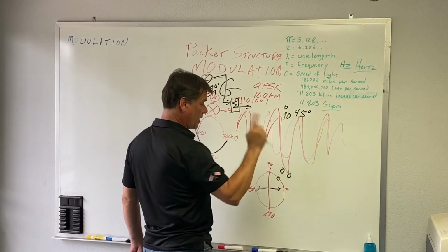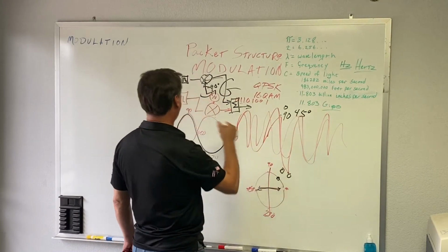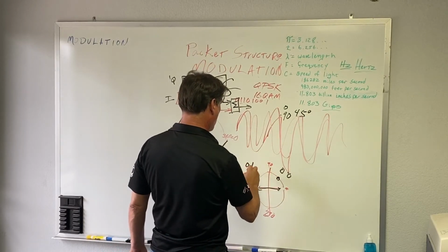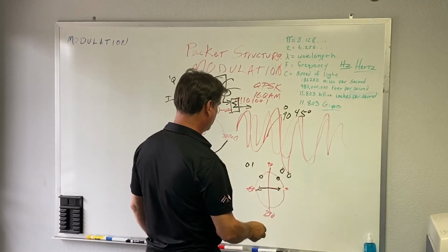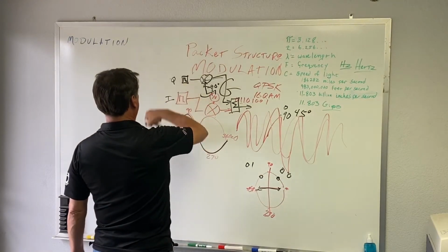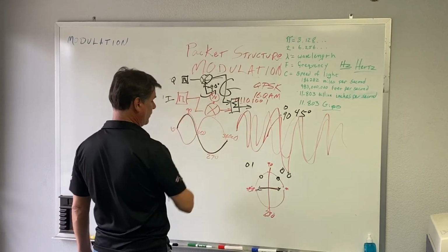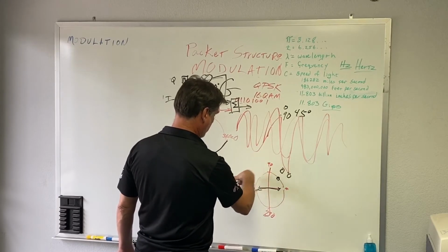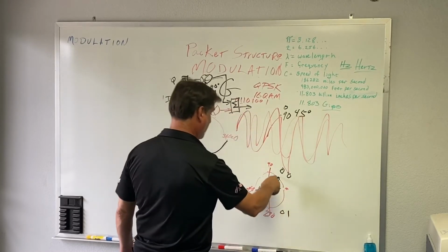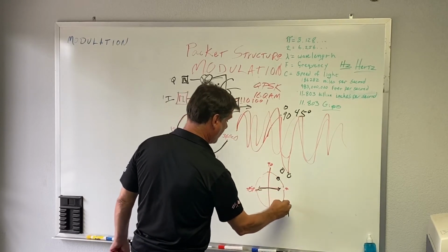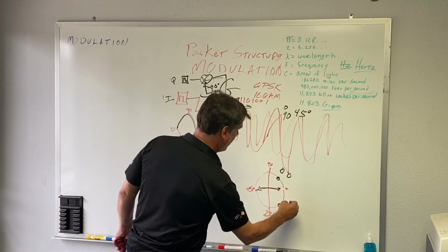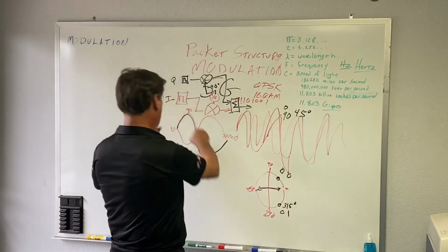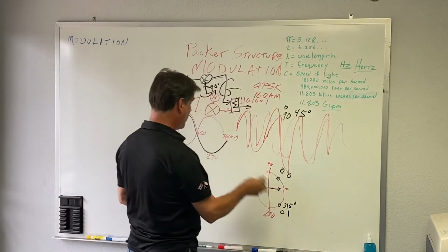When you mix these two, you get the difference between them. So if you go to a 1 here on Q, so that is going to be a 0, 1. We're going to shift it right there. Take that guy, make him a 0, make him a 1. 0, 1. Because Q by itself had changed down to there, so our new vector is there at 315 degrees. That's a 0 and a 1. It's 2 data streams. You're just changing the vector.